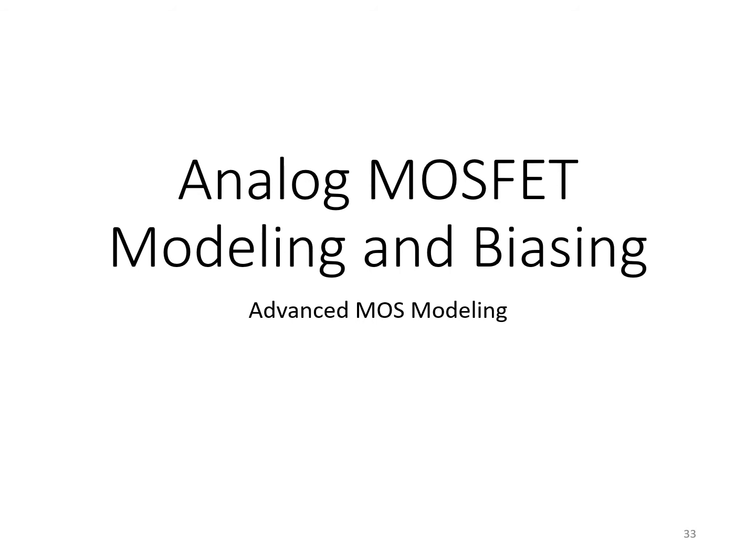But it's still nice to have the simpler models as an intuitive guide when you're doing design of, let's say, an amplifier and you want to know whether to increase or decrease the size of a transistor. Well, it's really mainly the first order model that's in your mind that you're using to figure out what will be the positive and negative impacts of, say, decreasing the channel length or increasing the gate width, right?